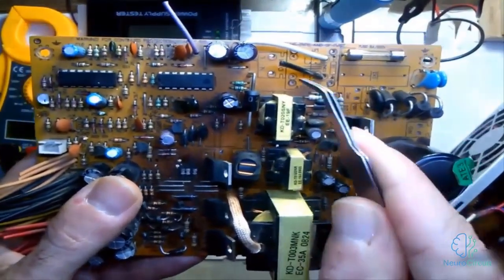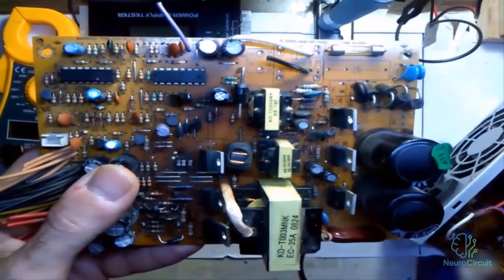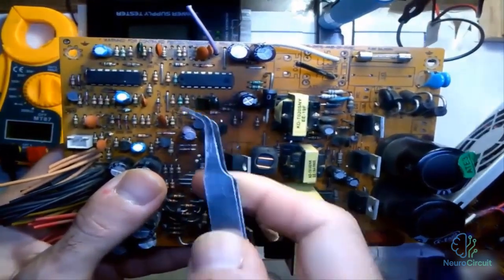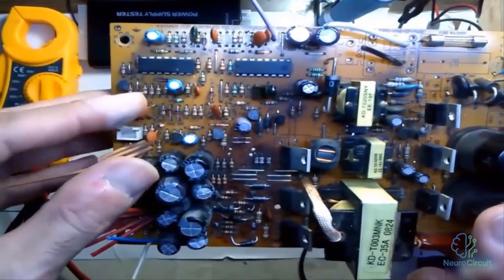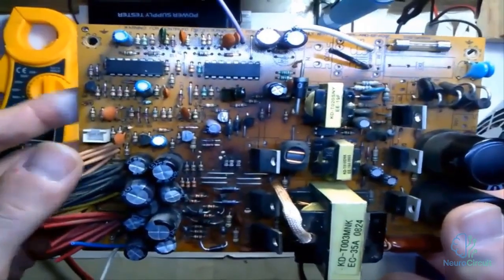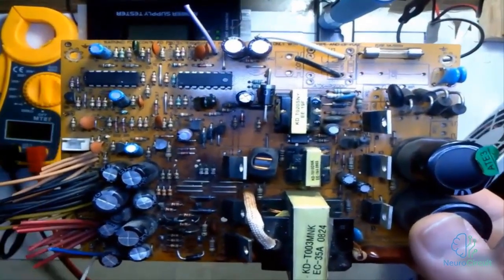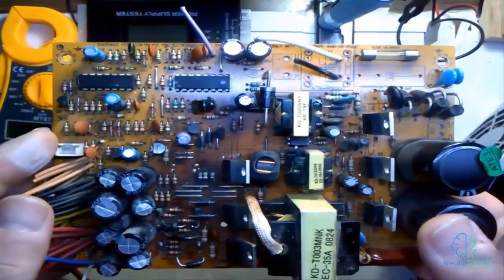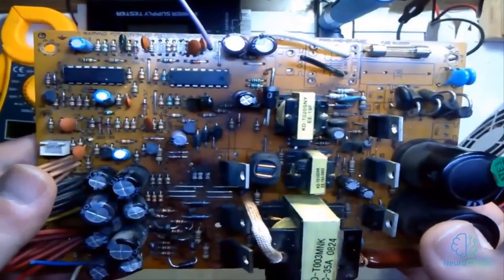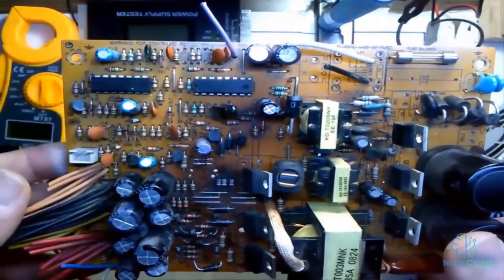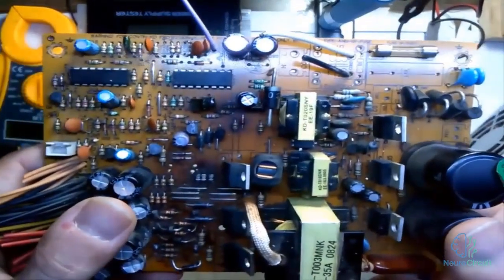Switching power supplies, since they are made up of different sections, can have each section fail independently. For example, if the overvoltage circuit of a switching power supply becomes faulty, when the voltage in the circuit exceeds the limit, it is supposed to signal the control circuit to shut down the power supply. But this doesn't happen, and the power supply stays on and keeps running right up to the point of failure. So, by troubleshooting step by step, we can determine whether the control circuit is working properly or not, whether the overvoltage protection circuit is functioning, and whether the standby circuit is operating correctly.